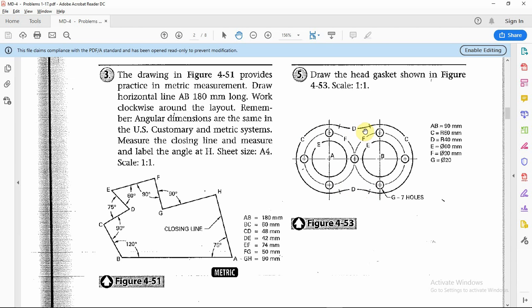We'll get into that. And again, knowing that those are tangent points or tangencies is useful information, as well as seeing, now we have the dimensions, obviously. We have some things listed or given in radius, such as C and D, and then we have some things like E, F, and G given in diameter. The standard is if the curve is a complete circle all the way around, then they're going to give the measurement all the way across, being your diameter.